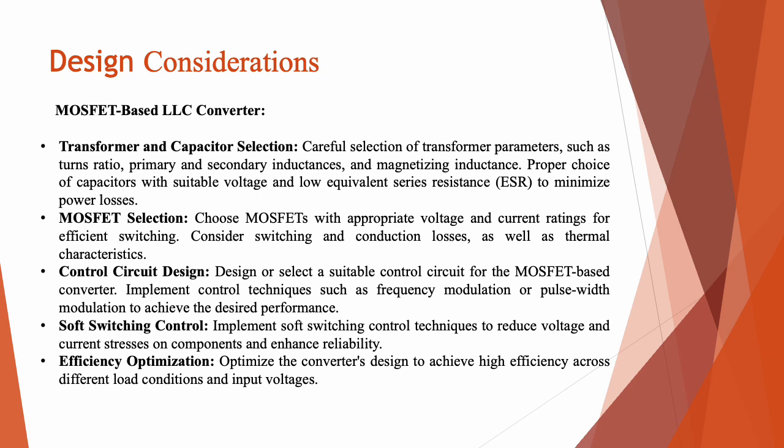Now we are going to start with the design considerations. First, the MOSFET based LLC converter. In this, we have selected the MOSFET with appropriate voltage and current ratings for efficient switching. We have considered switching and conduction losses as well as thermal characteristics.